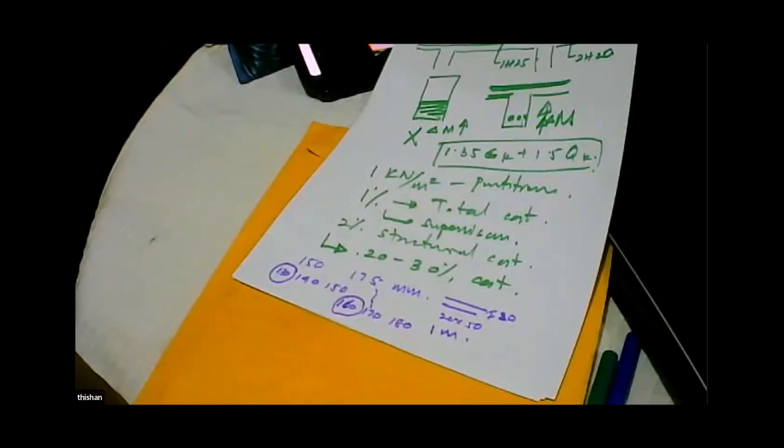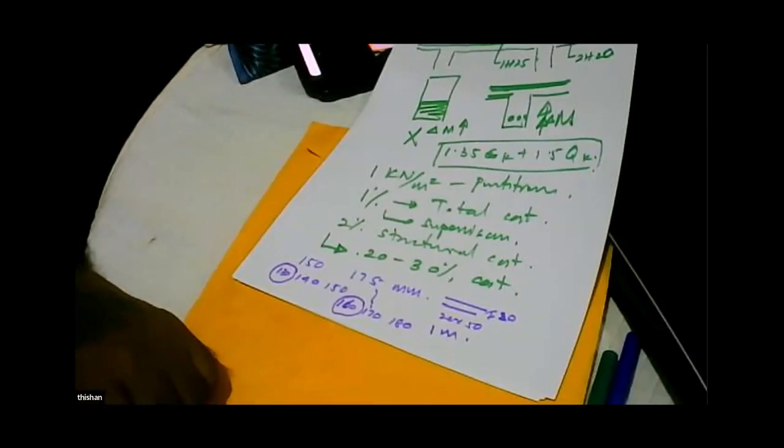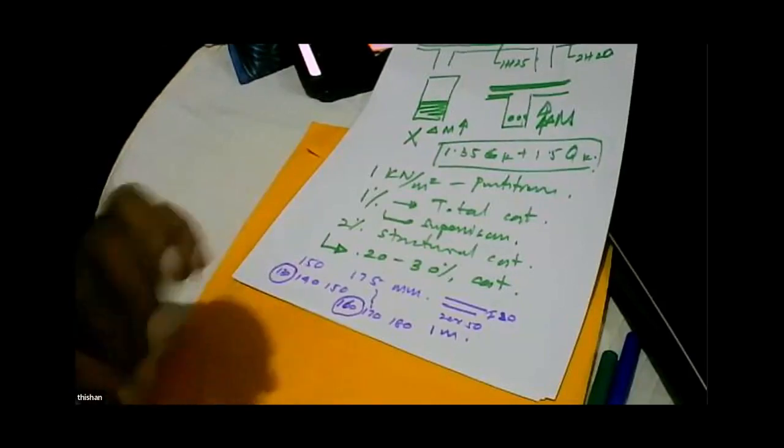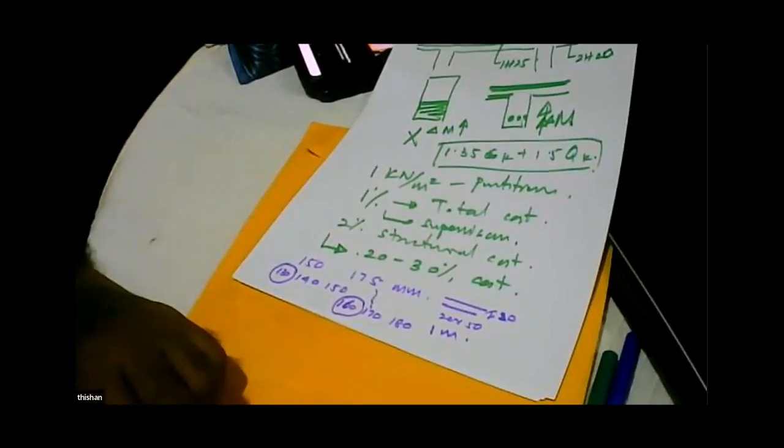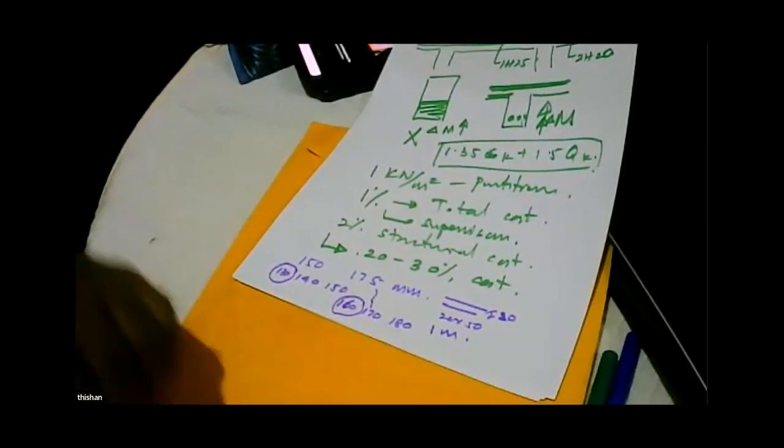So you will not do one calculation. You will do two calculations. One for 160, one for 170. Calculate the steel quantity with a rough detailed drawing, and then you decide whether to use 160 or 170 in this 50-story building. Why? Because if you save 10 millimeters, you are going to save 500 millimeters, or 50 meters.